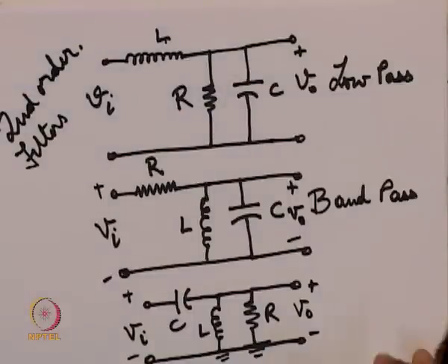Then let us see, on chip an inductor is very difficult to implement, because an inductor has a significant height, so it sticks up from the board. A simple implementation of an inductor using op amps can be done. So, we can replace an inductor with an op amp based circuit as follows.